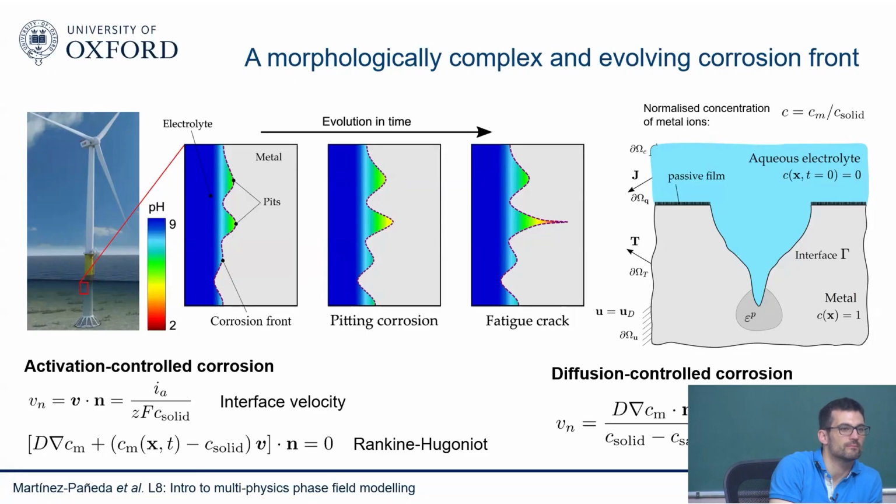A small follow-up: the depth or the amount of electrolyte on a wind turbine would not typically be a bulk solution. Some of your underlying physics may or may not be consistent, because it's atmospheric, so the film thickness of electrolyte on the turbine matters. You have a change like here, right? This is what you mean? So you will have a change from bulk to local defects. So they see pitting and this kind of thing. These are carbon steel, so they pit pretty quickly. But since you are solving the electrochemistry, you will see that change in local conditions. So you will know what happens, what the condition is near your pit.